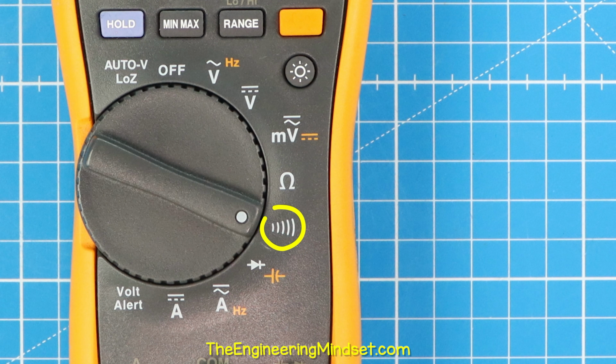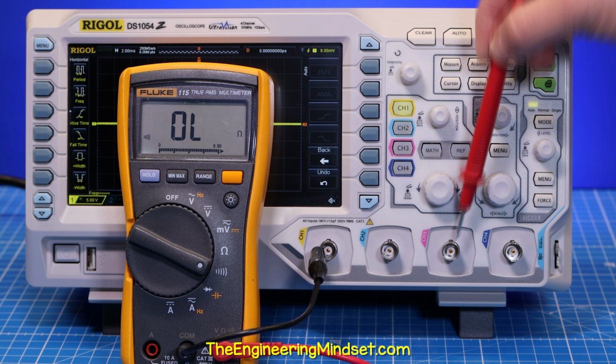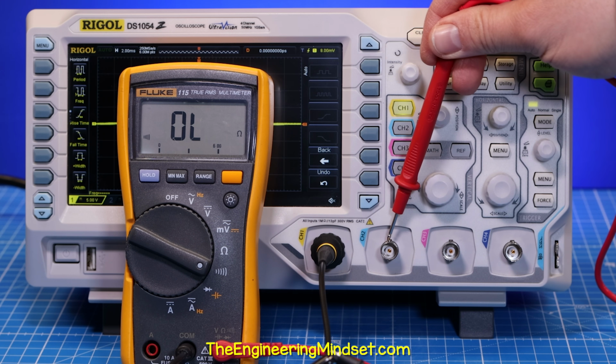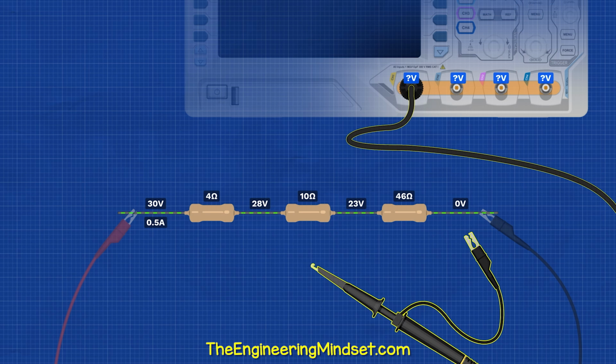Using the multimeter continuity function, we can see there is a direct connection between all of the channel grounds. There is also a connection between the ground clip and all other channel grounds. This has a very low resistance, so we always connect the ground clamp to the ground reference point.